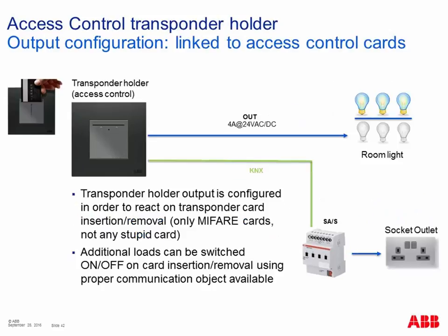The second configuration of the output is linked to access control cards. What does it mean? It means that I insert a valid card, a MIFARE card programmed via MiniMAC, into the card holder, and the output is a relay, so closed or open when you insert or remove the card.